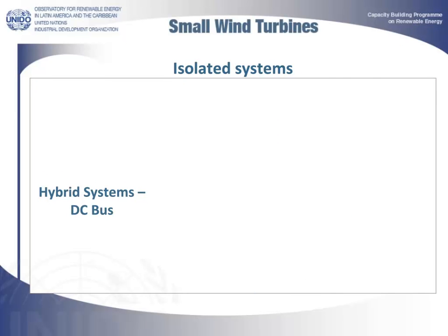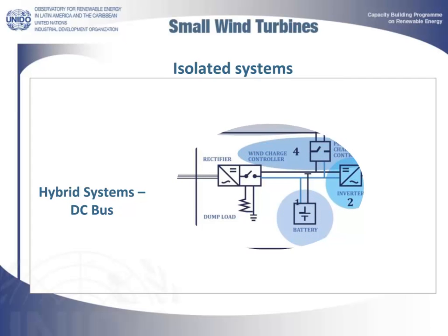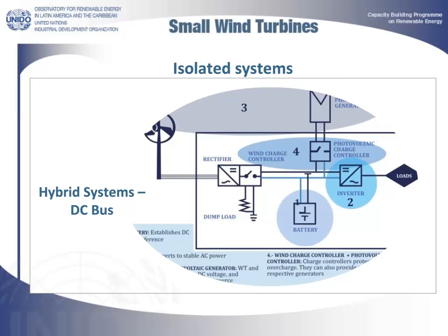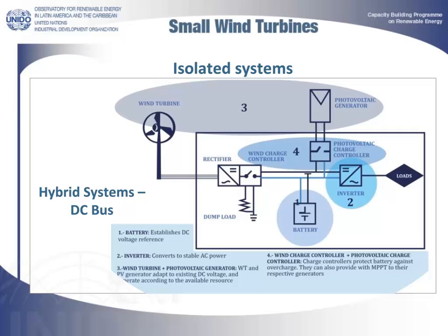In such systems, the grid is initially established by starting the diesel engine. Once started, the grid is set and loads can be connected. Once this has been done, the overall control of the system can allow the wind turbine control to connect when it considers this appropriate. But what if the wind power is greater than the load power?